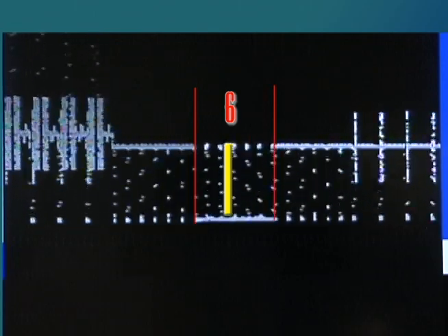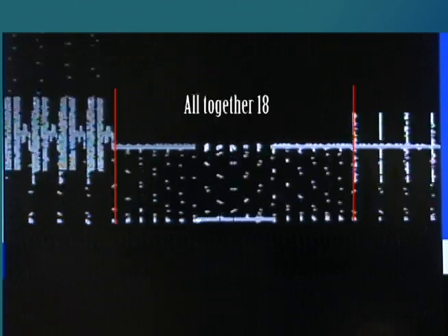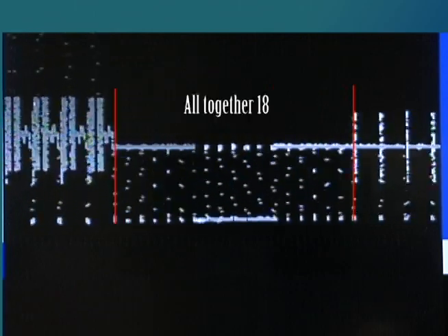There should be at least 18 dashed lines in total. They represent the 6 leading equalizing pulses at the 0 level, 6 vertical sync pulses at the -40 level, and 6 trailing equalizing pulses at the 0 level that make up the vertical blanking interval. There may be an additional 3 pulses at levels anywhere between 0 and 100. These additional pulses could be captioning, network cueing, or other broadcast test signals.